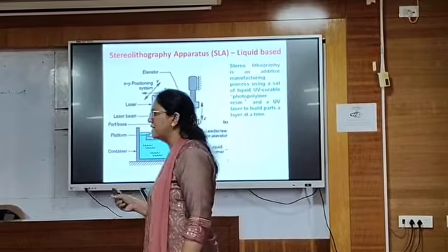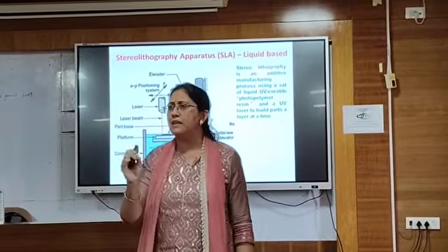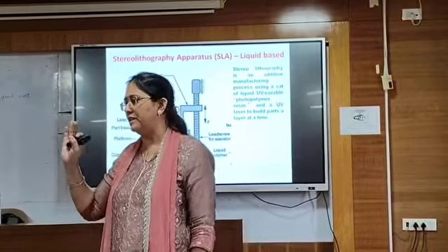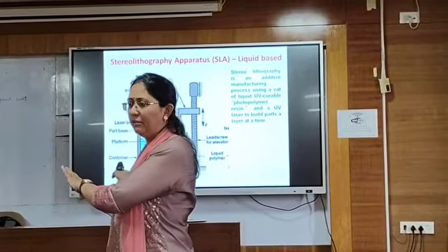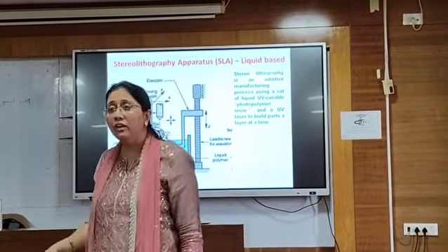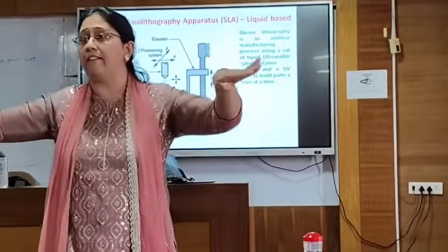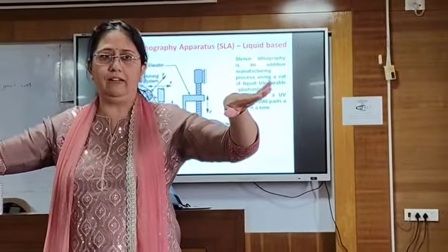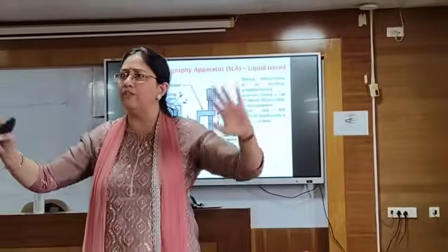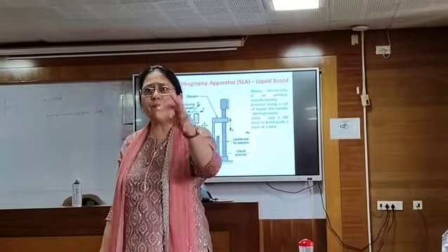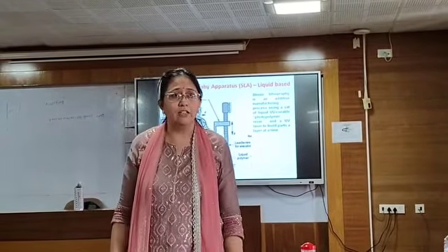Now, why resin based? Because it is a resin material available to you, not a thermoplastic, which you are going to convert into a very thin layer of solid material. Liquids, you are going to convert into solid, and the concept is called photopolymerization.